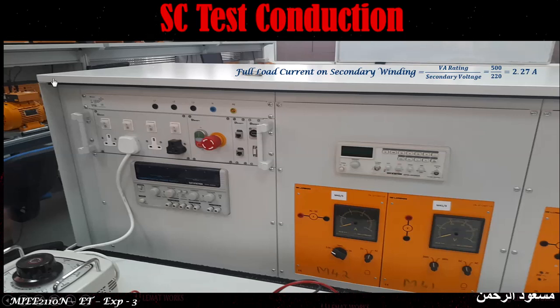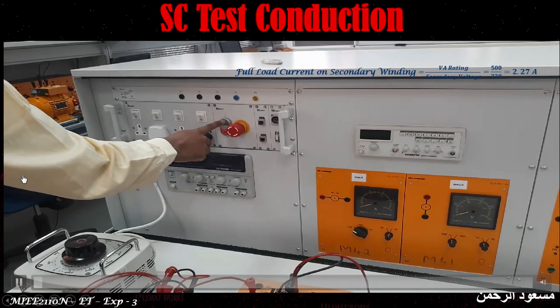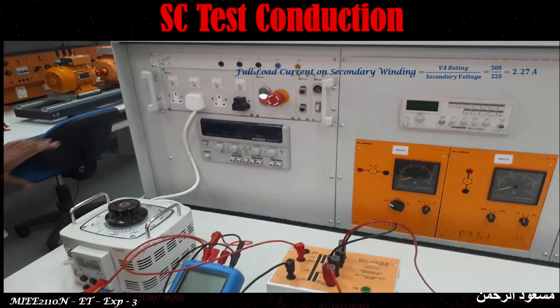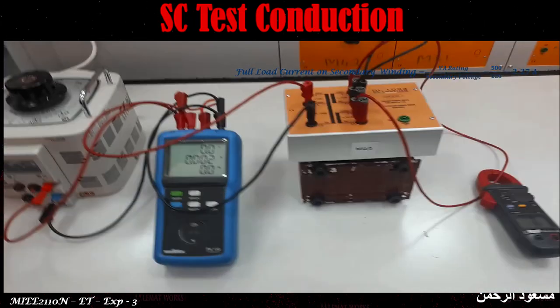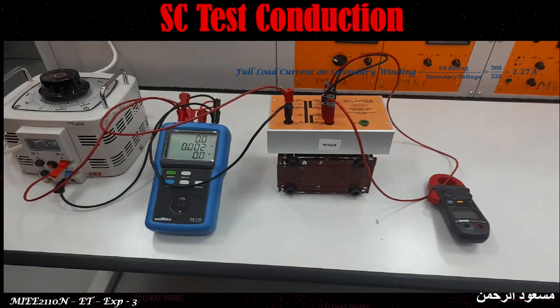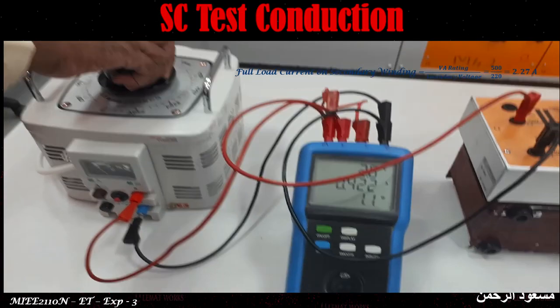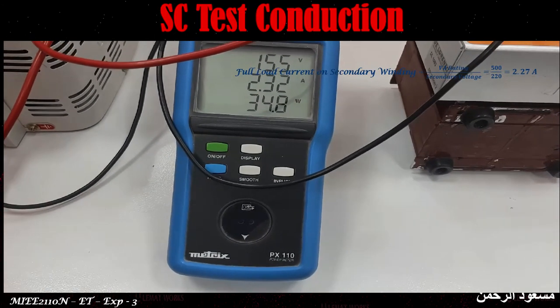Okay, now we will start. You can see the connections are given as per the circuit diagram. The table supply is on, and ensure that the auto transformer is at minimum position. Now switch on and vary the auto transformer gradually, very slowly, because the current will increase very steeply.